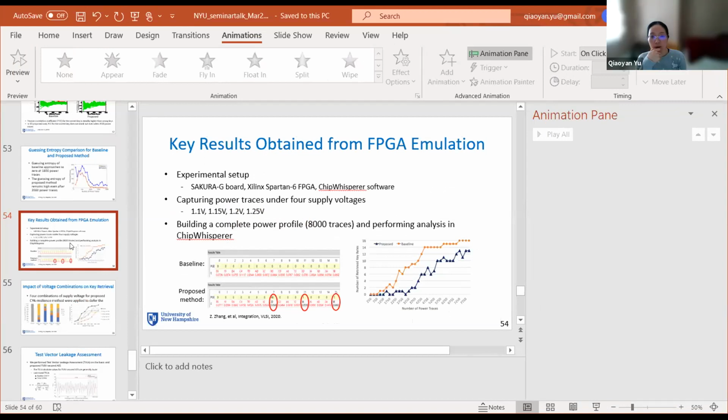Yes. So the point we want to make is that if we do the comparison, we will see that our countermeasures do not thwart the CPA attack completely. They just slow down the CPA attack, the key retrieval speed. That is the point to make. This is only for the experiment on one S-box. If you consider that you have multiple bits to retrieve all the subkeys for one AES, then it will take many more power traces. So when you slow down the CPA attack success speed, it still makes sense, although it's not completely thwarted.